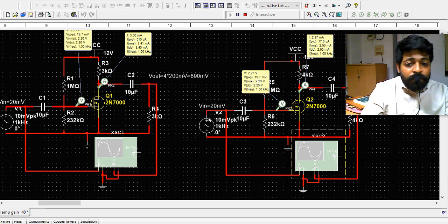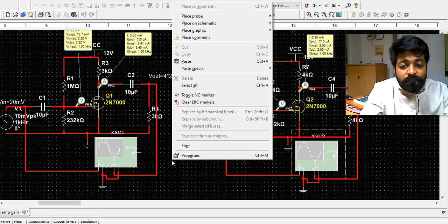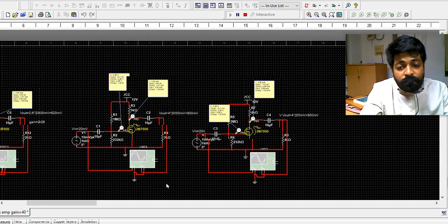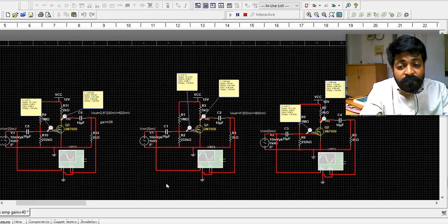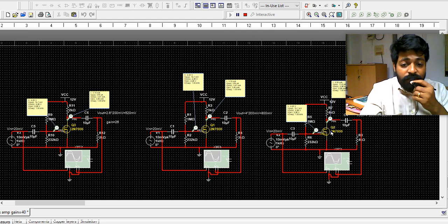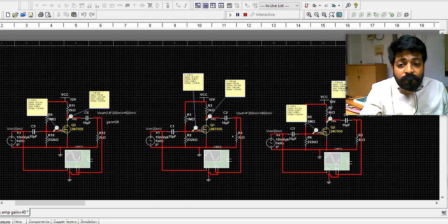So we saw how we can increase the gain by increasing the RT, and what the limitation is while increasing the gain. We cannot keep whatever resistance we want, and with the maximum resistance, the transistor deviates from its region of operation, and the amplifier fails in doing its task. That's what we observed here by observing the basic property of the transistor.